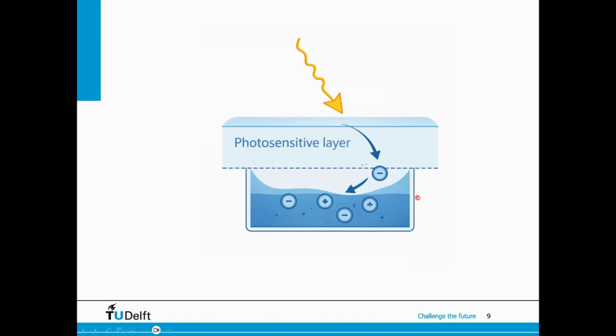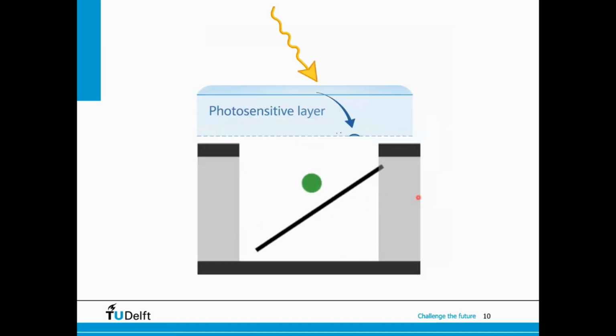The toggle has an extra feature in there, and it looks a little bit like this. So the photon still comes in on the top, it liberates an electron, and then on a pixel level, they have an electric field where they move the electrons to one end or the other. So we're basically having two registers, and we're taking two images at the same time.